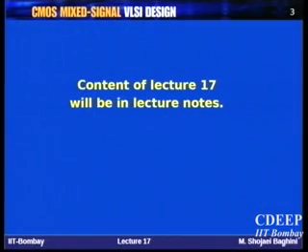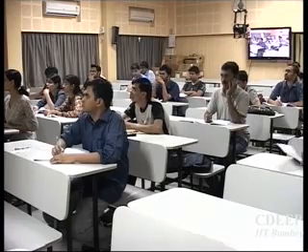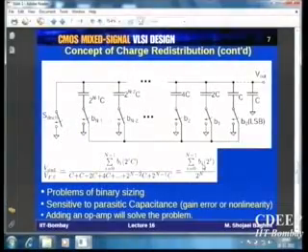So in this lecture I will write. Last lecture we were here where we have this binary weighted resistor array. Okay. Binary weighted capacitor array. And this is just a passive network. And we put an additional capacitor over here, which is C, to make the denominator 2 to the power n into C. That was the reason behind putting this additional capacitor. And therefore, when all are 1, we will get 2 to the power n minus 1 divided by 2 to the power n.